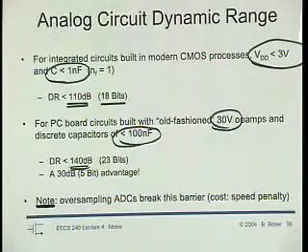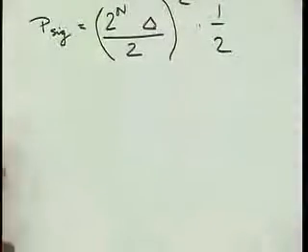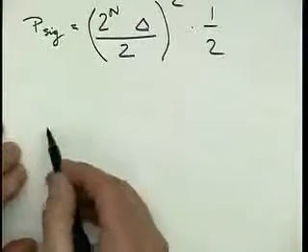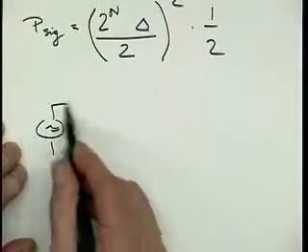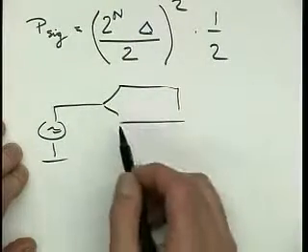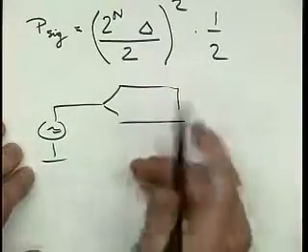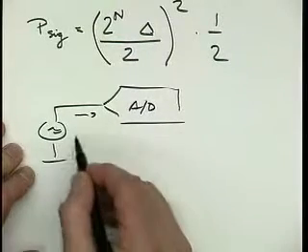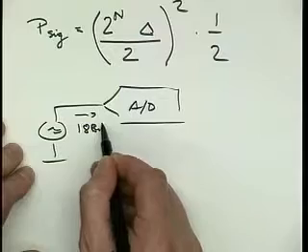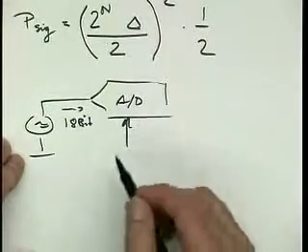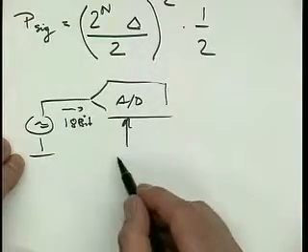I don't really want to go into that, but the basic concept is that you have your signal source, and you build your A to D converter, and you spit thermal noise into this thing on the order of, let's say, to the tune of like 18 bits. And you sample this thing at something like, let's say 4 megahertz.